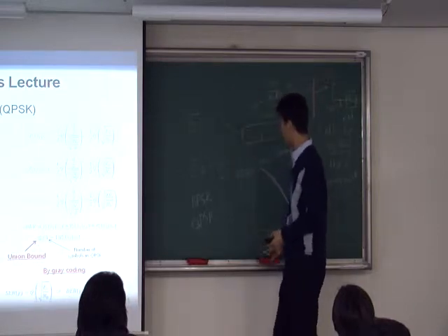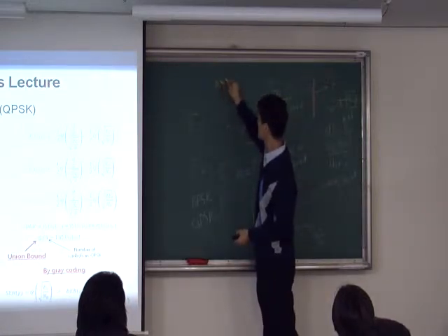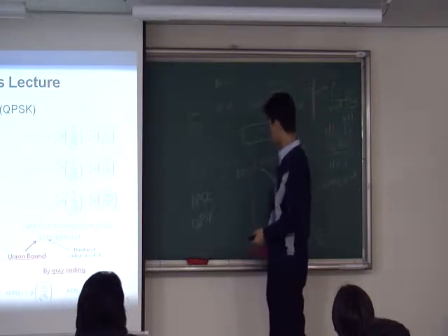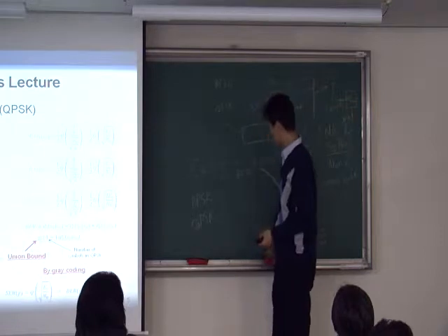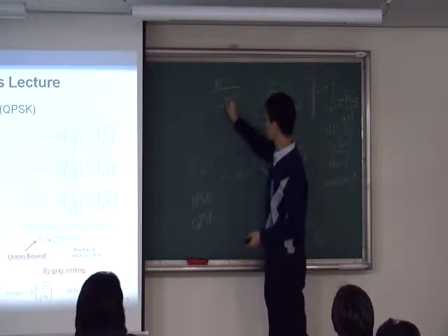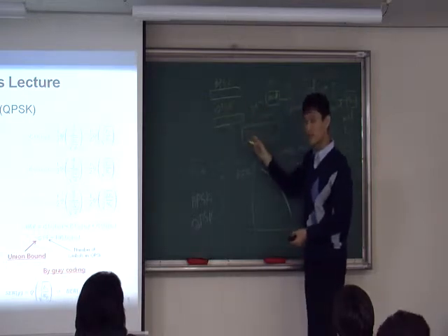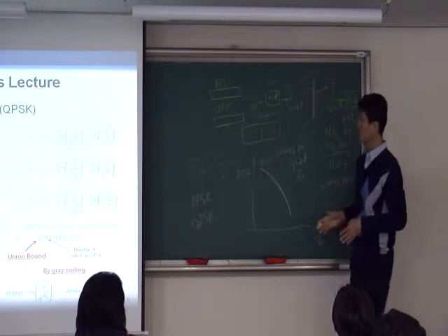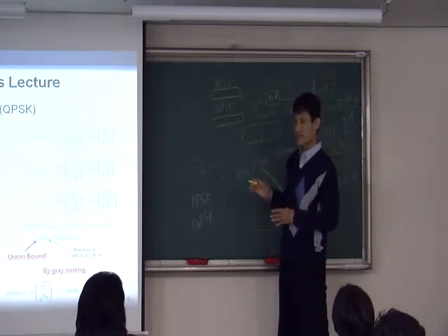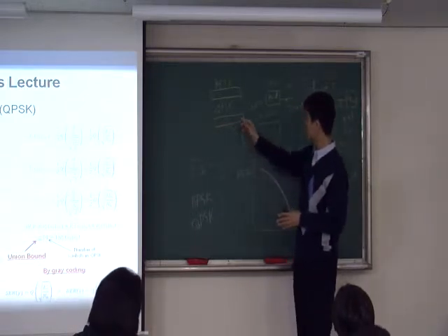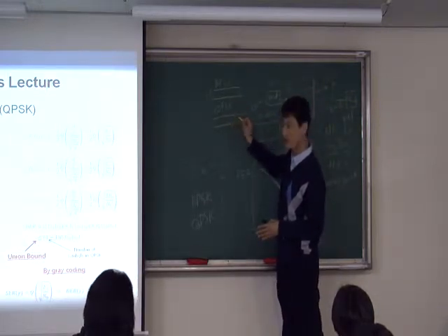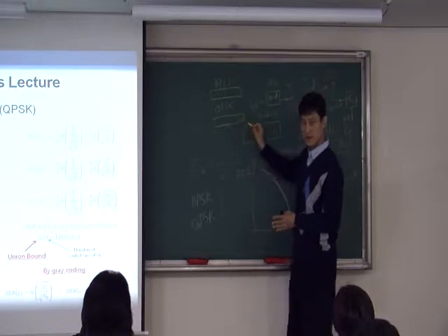Let's think about it this way. In BPSK, I have a symbol, and in QPSK also a symbol, same size, same symbol. I'm basically assuming the same sampling frequency, so the symbols look exactly the same. However, inside the symbol, this one is 1 bit, and this one has 2 bits, right?